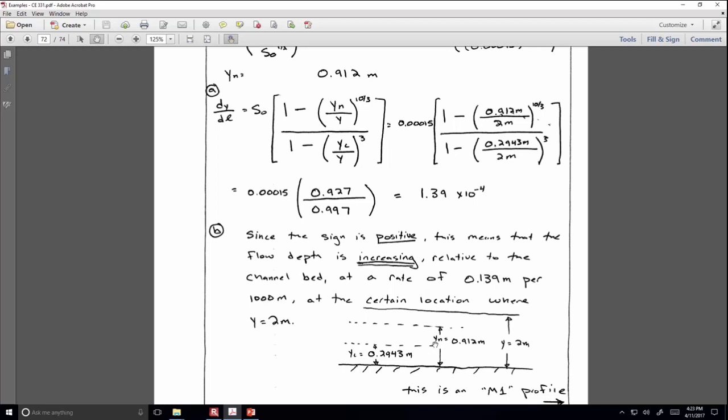subcritical. Now, zone 1 is the region that's above the first of these lines. Zone 2 is between them, and zone 3 is from the channel bottom up to the first of the lines. And so sometimes, like if it's a steep slope, then it would be the critical depth that is deeper than the normal depth. But here it's mild. And so our conditions are M1 because the water surface itself is in zone 1 up here, and M mild because the normal depth is greater than critical.